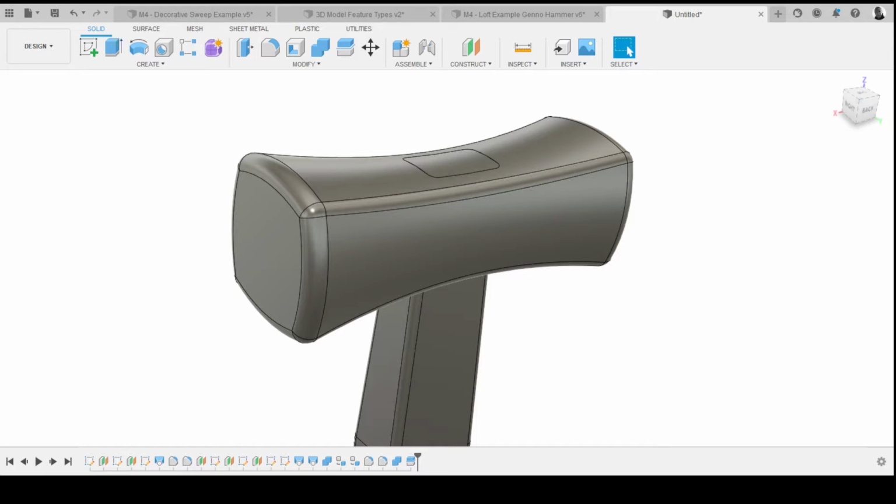If you remember, when I went back to the original way of lofting that hammerhead in two halves, and we had that geometry line running all the way through it, if I had stuck with that, I wouldn't have been able to use this technique because it would have that geometry line cutting through it, and you can only split with one face at a time. So there was method to the madness of doing it like this, and that just comes from understanding Fusion over a period of time. It also is good practice to not have those geometry lines in, as a way you can avoid them.